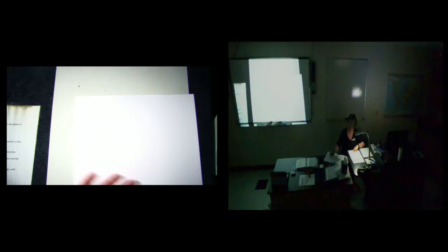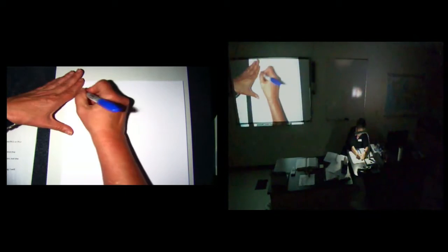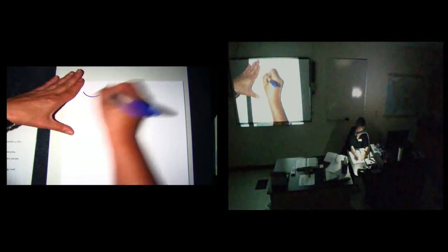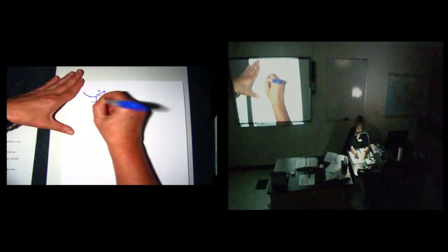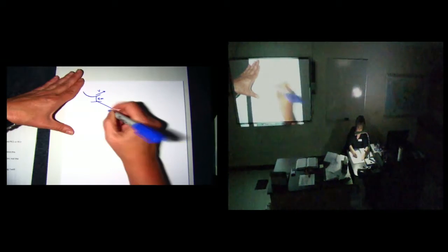So you start out at XA is equal to 0, and this is where A is, and that's where B is. YA is equal to 0. XB is going to be my 100 4/5, which is going to give me 80 meters. My YB, which is really kind of the trick to the whole problem, is I've got my 100 3/5 plus 4, and I end up at negative 64 meters.